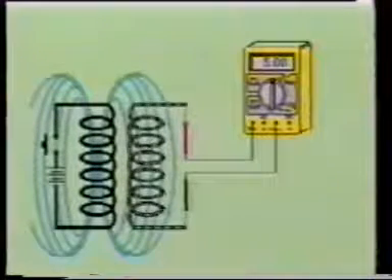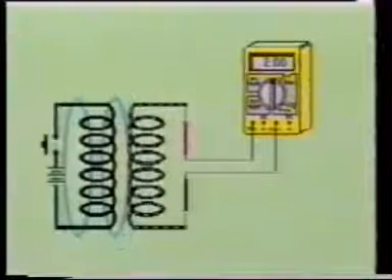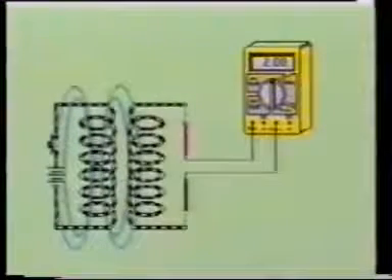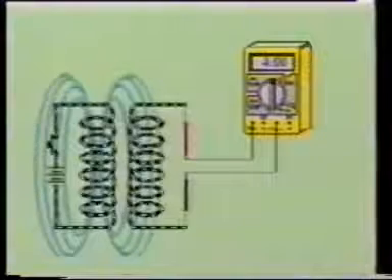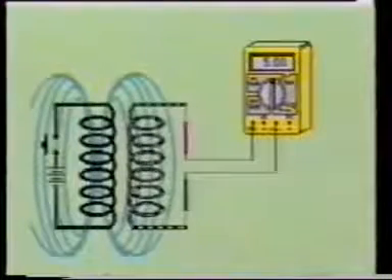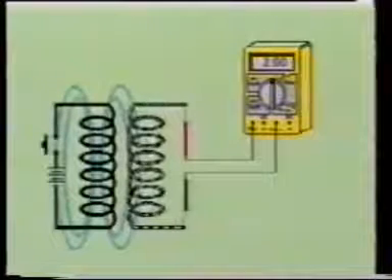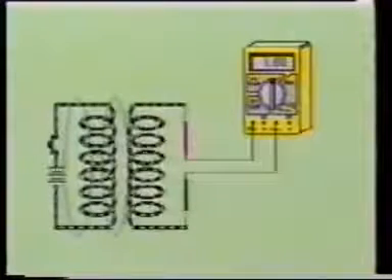If a switch in a current-carrying circuit is opened suddenly, there will no longer be any current to support the magnetic field, and it will begin to collapse back around itself. As the field collapses inward, a voltage in the opposite direction will be induced. This voltage could also be called a counter-electromotive force, but it is usually known as a self-induced voltage.